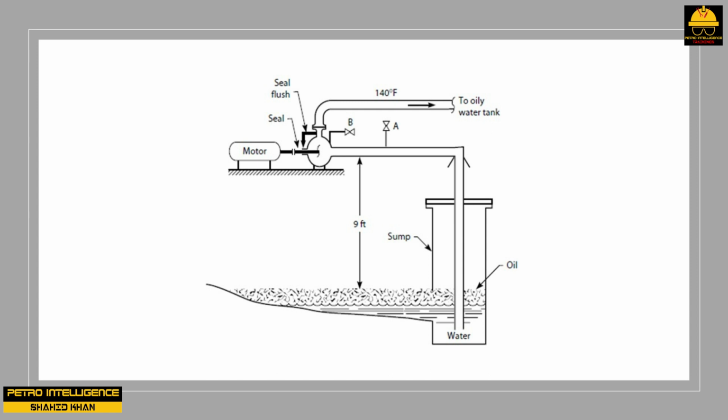In the picture, this is done by connecting a water hose to valve A and opening valve B. Air is pushed out of the pump case by the pressure of water in the hose. When the pump is in operation, the suction pressure of the pump is -4 psig. This negative pressure creates a potential problem.